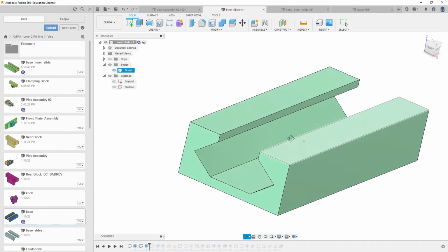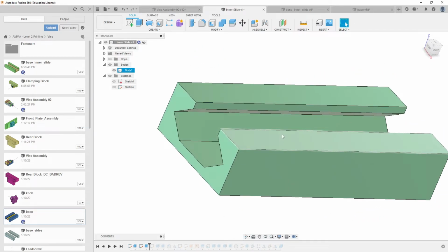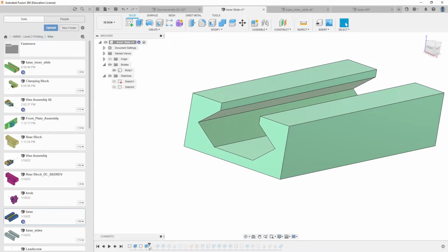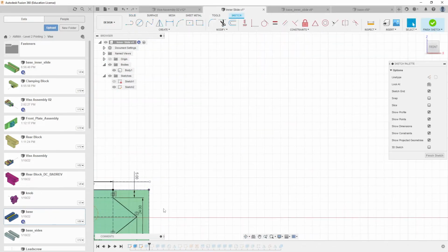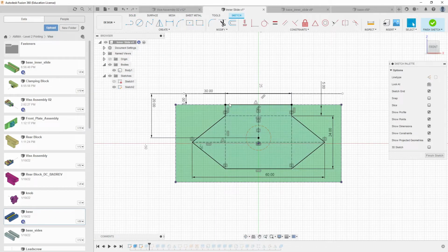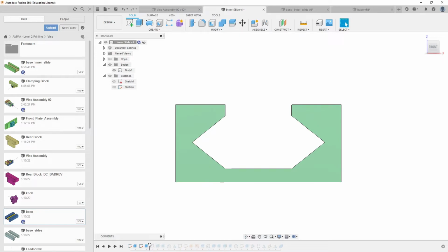I don't want to do it at the very end of time because it's going to cause problems, so I need to go back in time, but I need to be kind of careful where I place it. So in case I was concerned, I would look at the sketch that made this to refresh my mind. Does anything on this have a dimension that's based upon this edge right here? So for example, if this was an edge margin, that this was so far away from this edge, if I skinny it up, if I roll back time before this